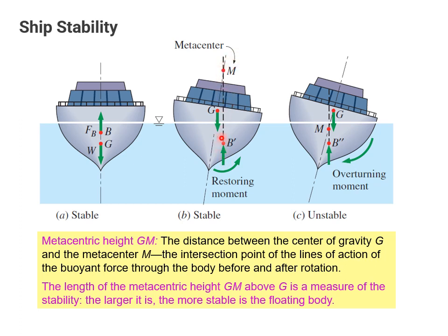And if you tilt it over the other way, what you'll notice, if you run the line of center of buoyancy all the way to the top, and you push the ship over the other way, the center of buoyancy line will actually cross at a point up above the center of gravity, which is called the metacenter.